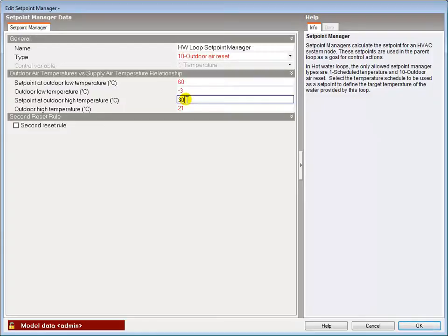Domestic hot water would need to be provided via a separate system, as the DHW flow temperature needs to be much higher than efficient space heating flow temperatures outside the peak heating season.